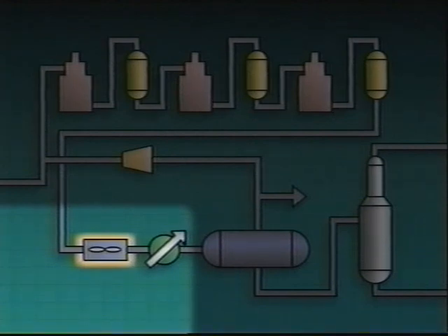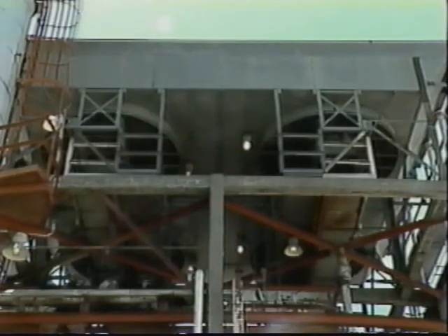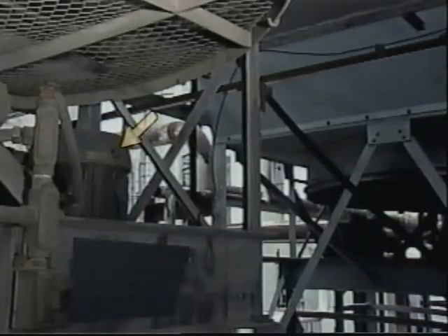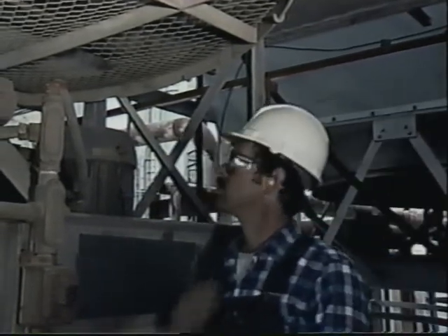This temperature is in fact too high, so the problem has now been narrowed down to the fin fan condensers. These are the condenser fans. After a closer look, it's discovered that one of the fans has stopped. And there's the problem. The fan motor has shut off. Without the fan, the product is not being cooled and condensed sufficiently.